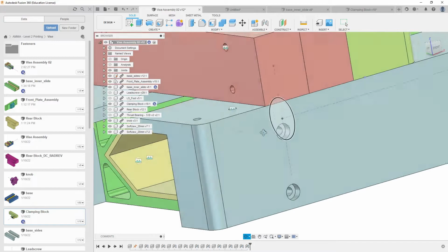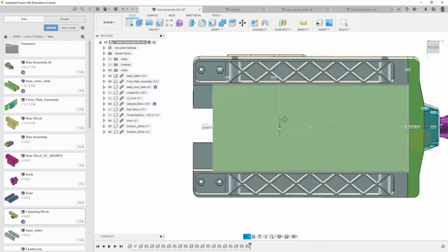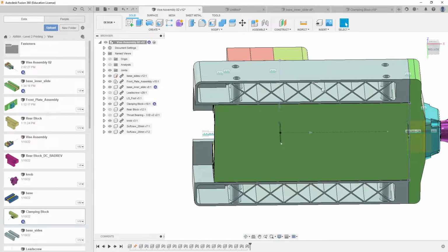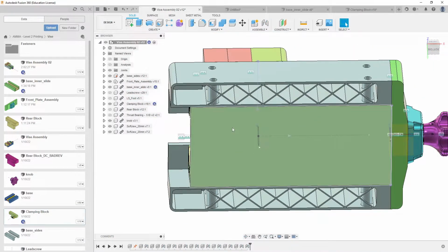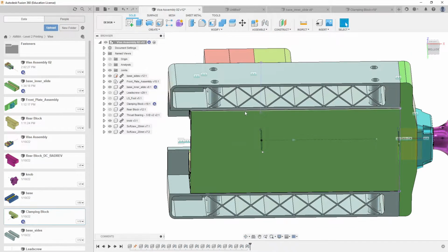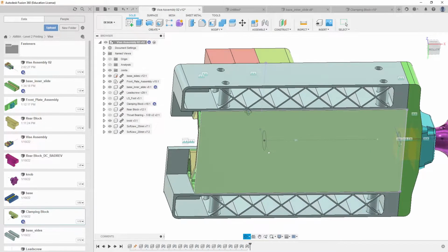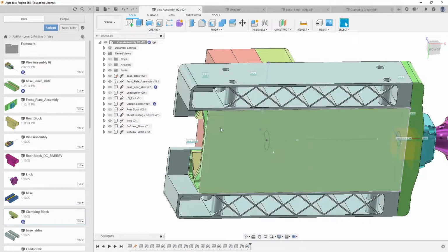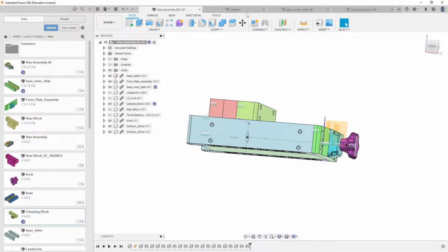However, if we go over here and we look at this, you see that this piece here is not the same as this. So think about it and go, is this going to be okay? Well, yes, this is being held inside here. So I'm okay having the holes on the green block here being symmetrical, even from the edge, but they will not be on the blue part, right? Which means that when we get to this blue part, now that you understand projections, or at least construction lines and that sort of thing, we're going to map out this green block on the side of this face here, so I can make these holes here still with maybe something like a centered rectangle, so it's even, but inside of this section that we quarantine off that's the same length as this. So for right now, pretty easy.